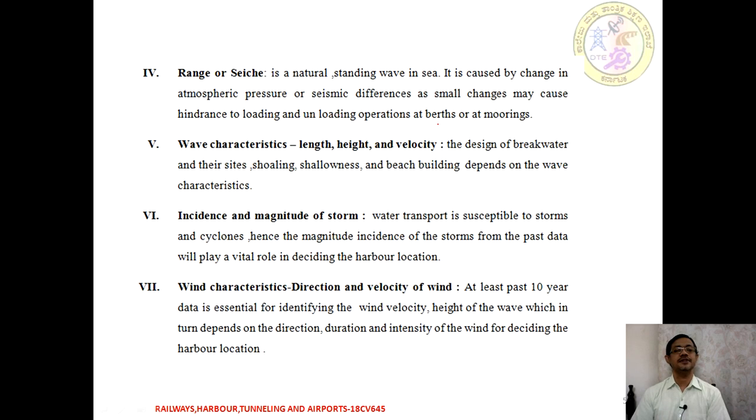Next is the wave characteristics. In the wave characteristics, the length of the wave, height of the wave and its velocity are to be measured. This is going to be helpful while designing a breakwater and its site, then the shoaling and the shallowness. Apart from that, the beach building also depends upon the wave characteristics. Hence, wave characteristics are one more important factor that needs to be considered while selecting the site for a harbour.